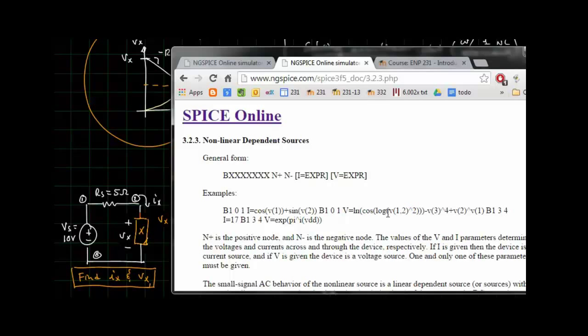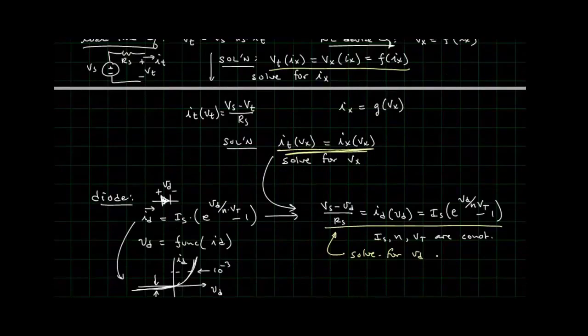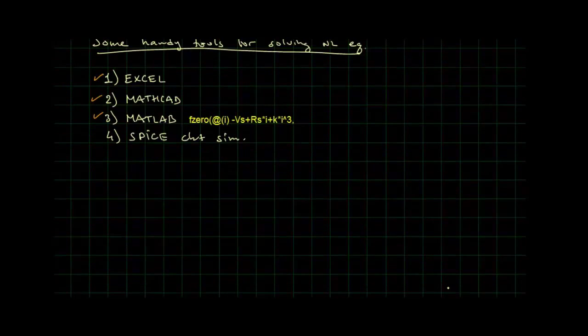So for LTSpice, if you're going to do I to the third, you would write the function PWR, power, I, 3, and that's how you would specify raising some variable to a power. Of course, you wouldn't put I, but maybe I of VS1 or something.